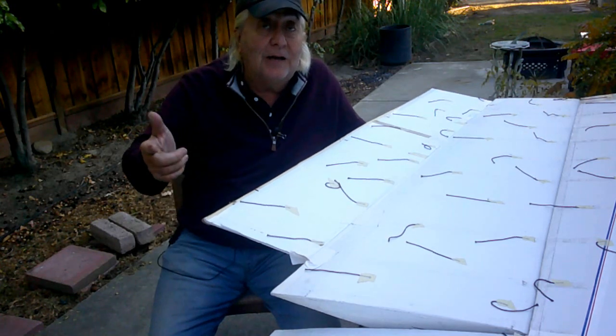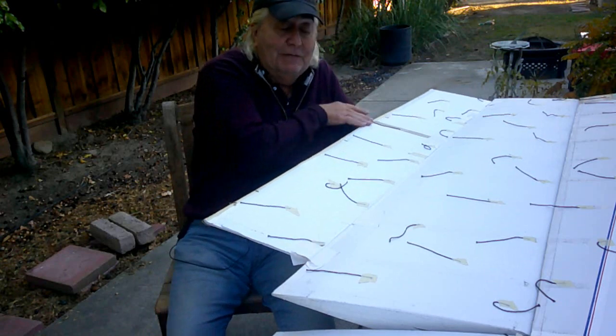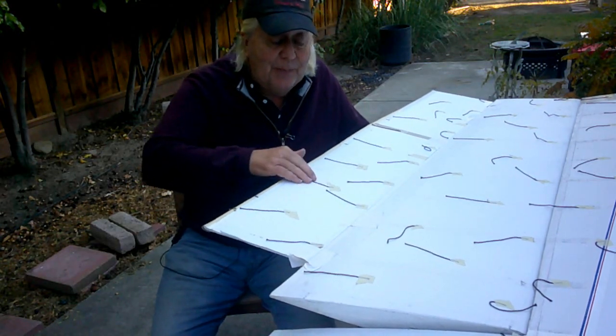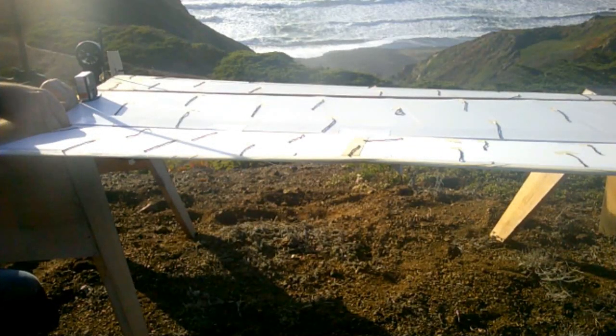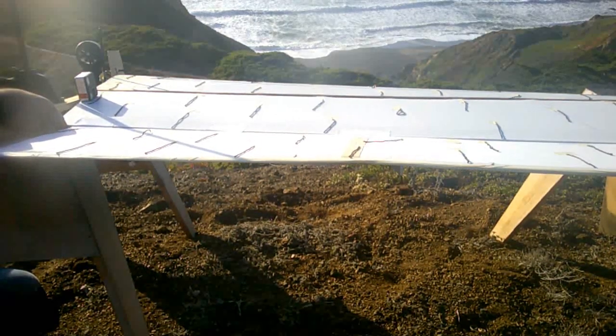I'll take you over to the video now and I'll talk through that video. But you're going to see some pretty nice flow conditions here. It really is a problem solver. So let's go take a look at that. Now, before I let this video roll, let me explain the weird angle you're looking at. Remember that the trailing edge of the wing is tapered down and the elevon attachment is a flat plate. So when the elevon attachment is aligned with the chord of the airfoil, it looks like there's a big kink in the wing. And there sort of is, but the camera angle and so forth makes it look much more drastic than it really is.